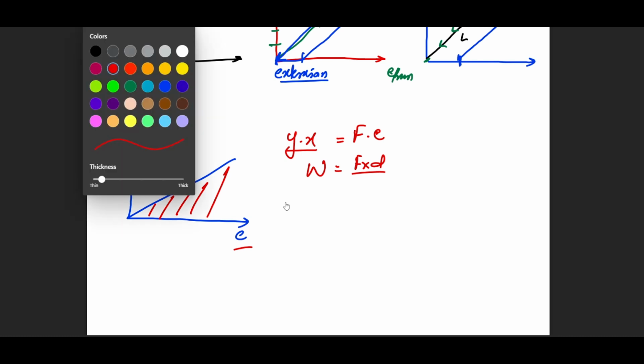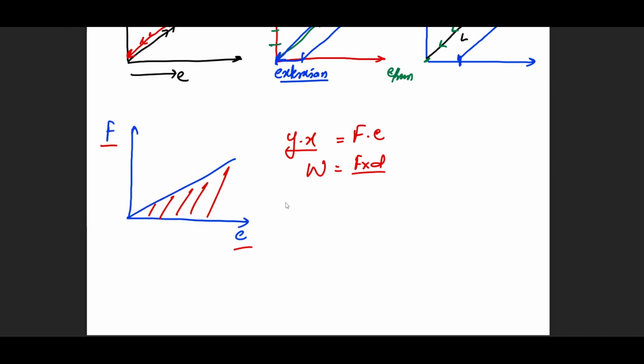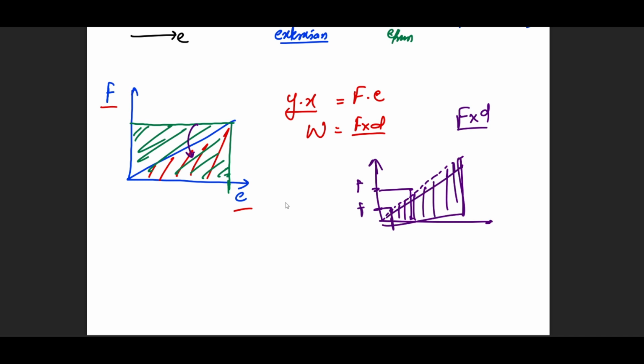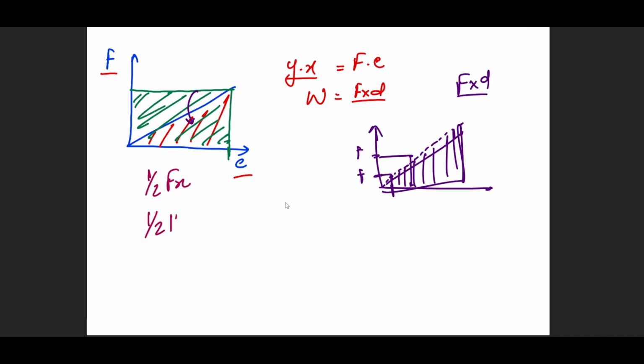So he sometimes asks why the energy is generally half. What happens is that the energy that you provide to the system is actually going to be this much. You provided this much force for this much extension. When you got the energy back, this will actually be half of what you've provided. Under the best of circumstances, this is what you are going to get. Another perspective is to notice that if you are applying less force, then you've moved less distance. If you apply higher force, then you move higher distance. So at every point, there is going to be a variable answer of F into D. Combine all of those answers together by an integration formula that you do in mathematics, and you get this idea again. That is going to have a factor of 1 by 2, half Fx, and you can see a formula of half kx squared as well. If you replace F equals kx in this formula, you get this one.